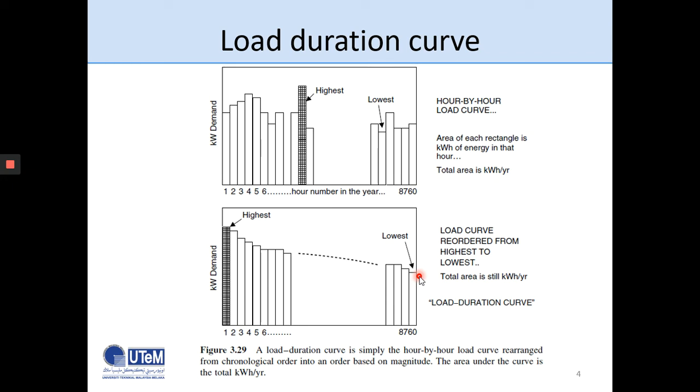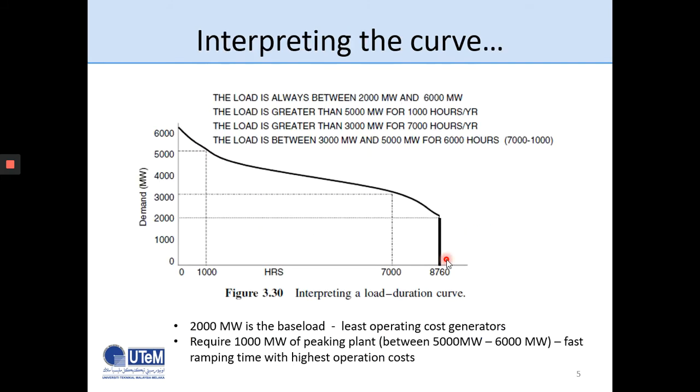We do this because we want to know what is going to be our load profile or load curve profile throughout the year, so that we can arrange our resources to fulfill them accordingly. Okay, here's what I mean. Now, once we have already rearranged from highest to lowest, we can obtain a figure like this. Okay, this is just an example. So let's say after you rearrange from the highest to the lowest, you will get this figure.